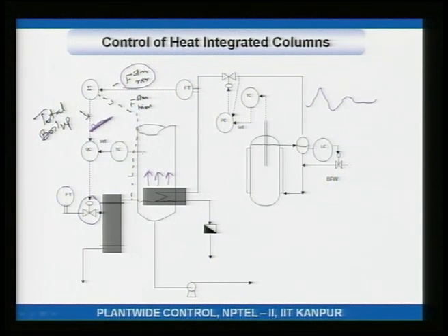Okay. So, earlier variability in the steam rate from the reaction section was causing the boil up to vary. Because the boil up was varying, the temperature varied, and in order to bring that temperature back, I adjusted the trim duty. Now, here the steam from the reactor is varying. However, as the steam from the reactor goes up, the total Q controller reduces the amount of steam to the trim reboiler.